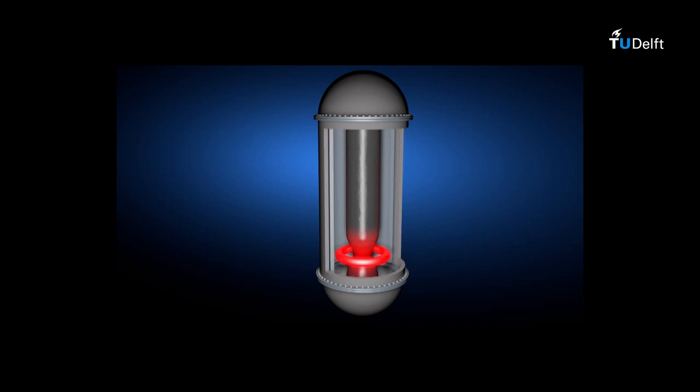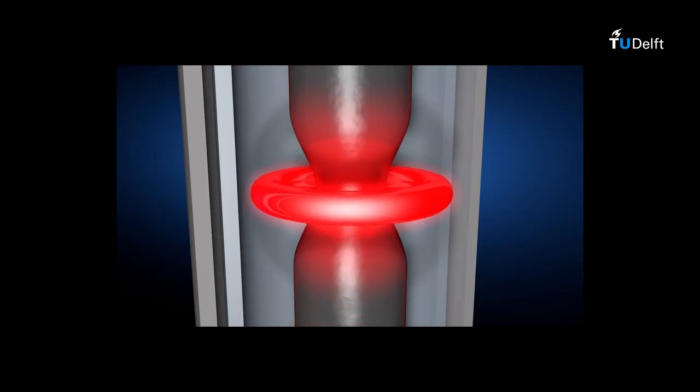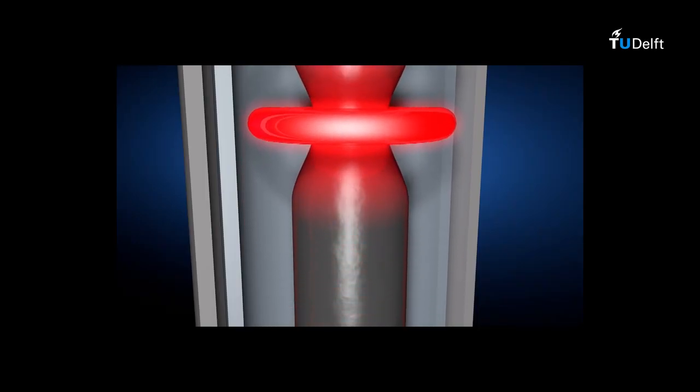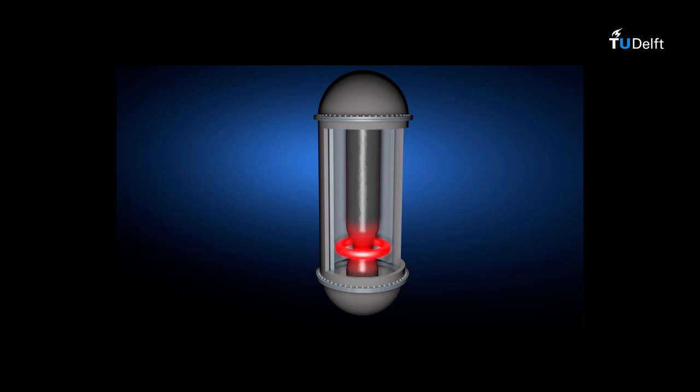The end of the rod is heated up and melted using a radio-frequency heating coil. The melted part is put in contact with seed crystals. Here it solidifies again and adopts the orientation of the seed crystal. Again, both 100 and 111 orientations are being used. As the molten zone is moved along the polysilicon rod, the single crystal ingot is growing as well. Many impurities remain in and move along with the molten zone.